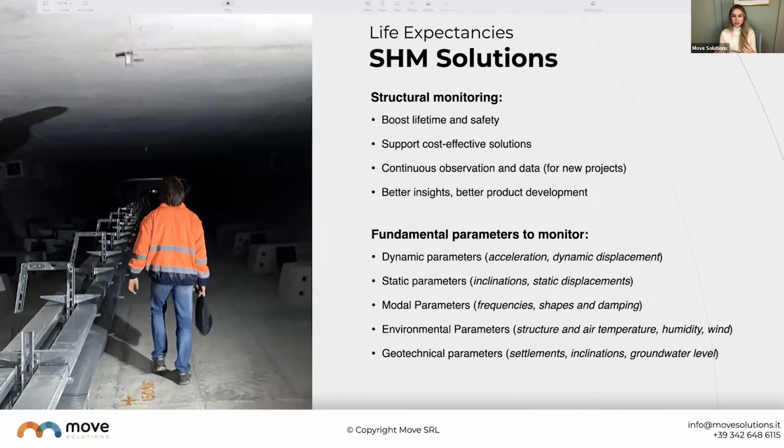So we're able to take those dynamic parameters and perform modal analysis, looking at the frequencies, shapes, and damping of the structure. And that's how you get that proactive response, because you're able to see slight changes in the structure long before you would see a static change. So before you see a movement on a total station, or before you would see a movement on a tilt meter, you're able to see those slight frequency changes.